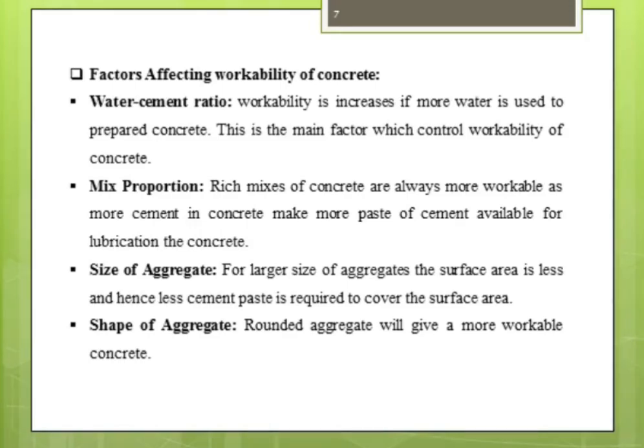That finer particle has more surface area, which requires more water demand. So ultimately it affects your workability, because it absorbs all the water onto its surface area, and the water available for the desired workability will be less. So that's why the mix proportion is also very important. Through the proper mix design we can calculate our mix proportions.